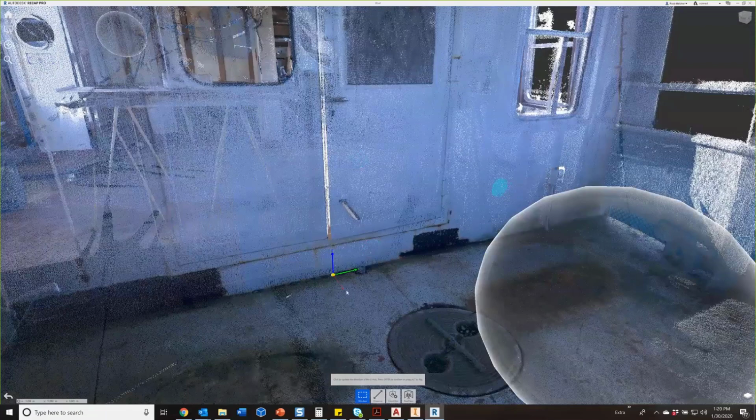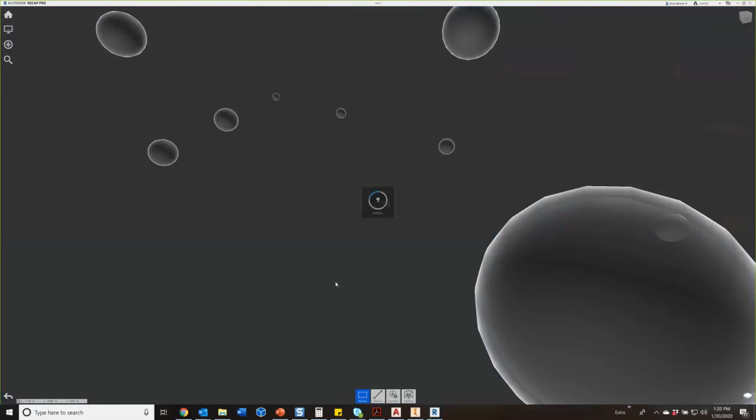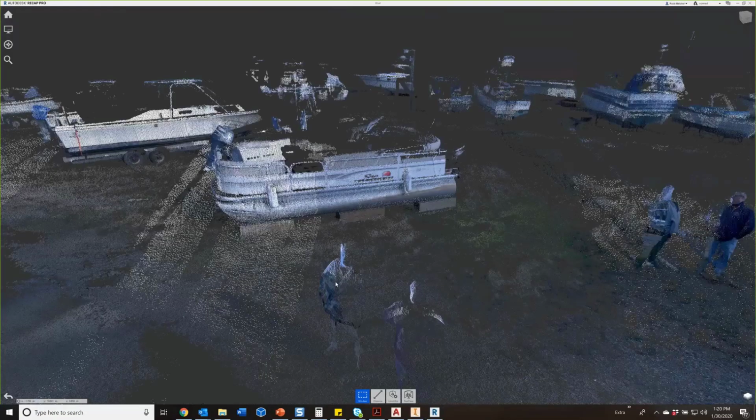Now, I've got my x-axis pointing aft. I want it to point forward, so I'm going to hit the Alt button. That flips it so the x-axis points forward. Once I have it set up the way I like it, I hit Enter. And now my UCS of the scan is in a known position, and I've defined which way the X, Y, and Z directions are set.